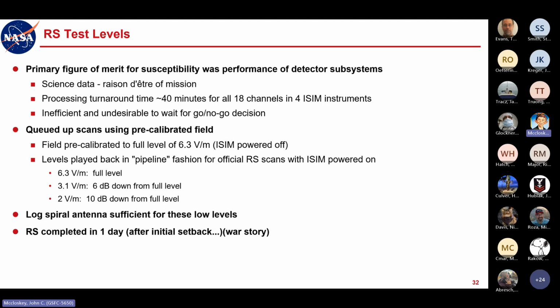Going a little further into the weeds here, at unit level tests, we saw some susceptibilities at frequencies that I was looking out for. In fact, I was pretty sure it was due to resonant cable lengths that were going to be different on the integrated ISIM. So I was predicting that those resonances, those susceptibilities, were going to shift in frequency. And it turned out they were right in the range that I suspected that they would be.